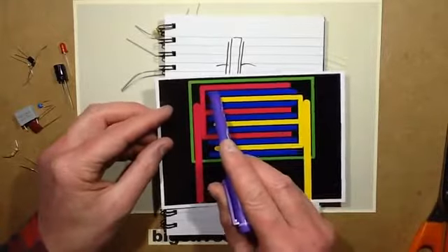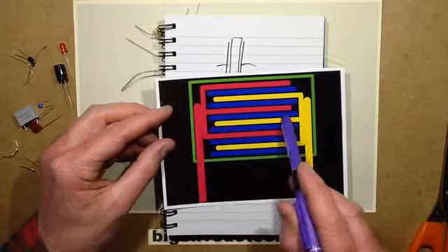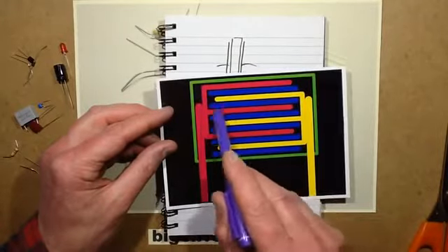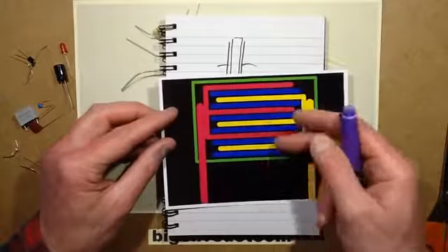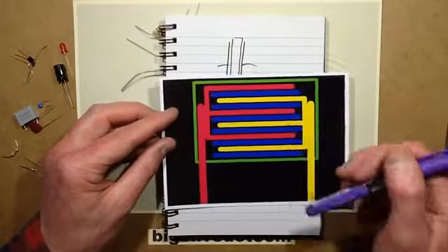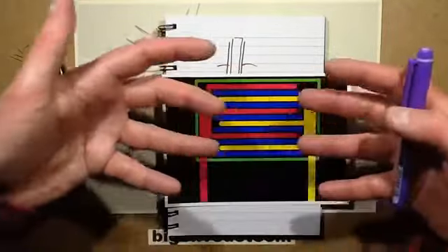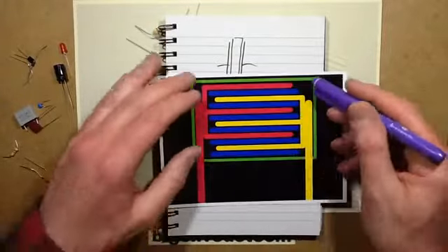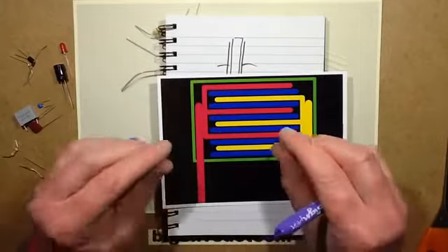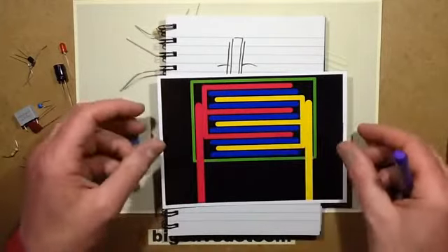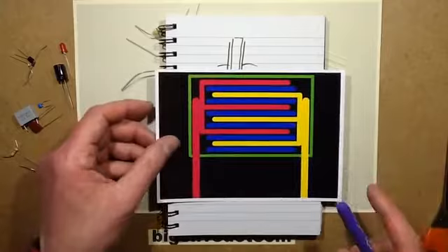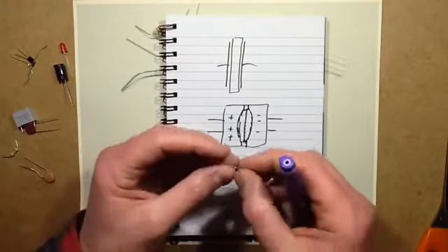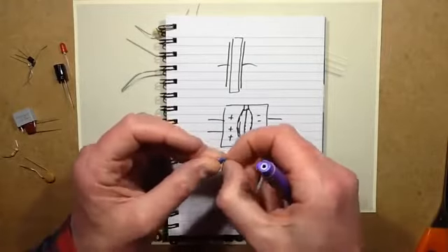And if you can imagine that the blue is layers of insulation in the ceramic capacitors, and these are metallized plates, then by alternating the pole, creating a sort of comb of them with insulators, and then putting a metallization down the end to connect them all together, you can create quite a large capacitance in a small area just by making it a multi-story capacitor, so to speak. And the layers of insulation in these are still going to be super thin. You'd need a microscope probably to see all the layers.